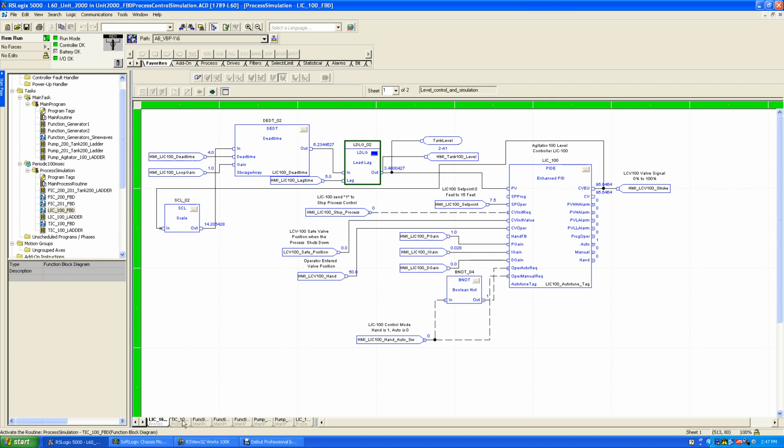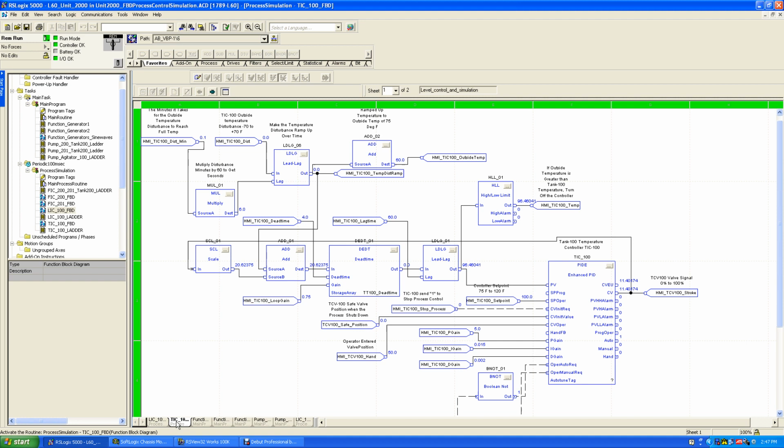Now, our temperature controller is a little more complex. We'll start down here at the bottom, at this line right here. This is the temperature controller. Here's our set point, and it's 0 to 200 degrees, and we've got it set for 100 degrees. And we come out of there and we get 0 to 100%. Even though we can scale this variable, this is just the CV itself.